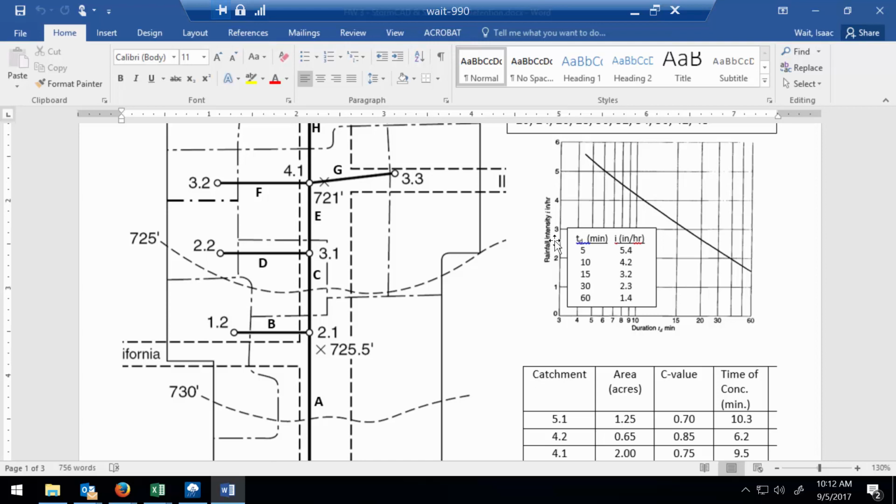Good. Slope, yeah. So it's actually going to use Manning's equation to calculate the relationship between flow rate and the pipe characteristics. And so the slope, the material type, the diameter. And so we can solve Manning's equation for Q, or if we know the diameter of the pipe, we can solve Manning's equation for velocity. And so it's going to know the length of the pipe, which we'll have to put into the system.